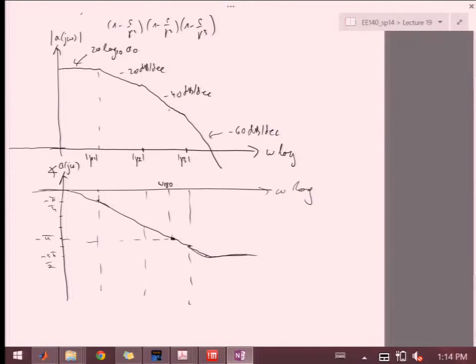And the important thing was that at that point in frequency, if your forward gain, which is A of j omega 180, is stronger than 1 over f, then your total A times f is going to be bigger than 1. And your total loop gain is bigger than 1, and you get instability because you're now passing the signal in positive feedback back to the input of the amplifier.